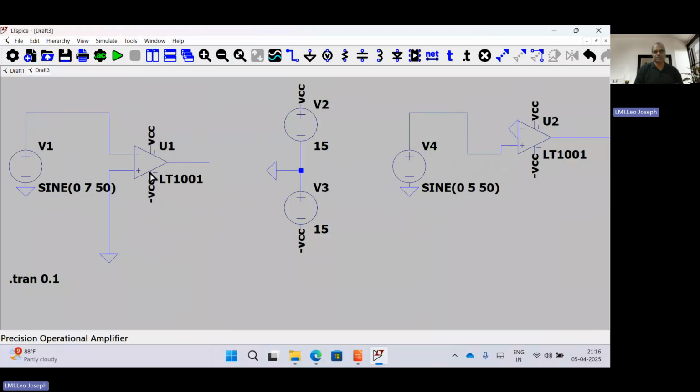I am using label nets here, so the cross wires are unnecessary and are avoided. You can also use a number of circuits in a single screen by using label nets. Unnecessary confusion in the wirings will be avoided. So you have to develop your technical skills by making the circuit understandable to those who are the users of the circuit.